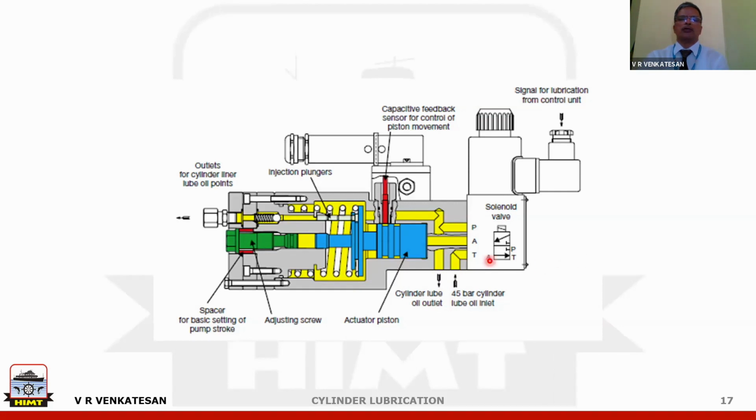So the principle of timed lubrication is that the cylinder lube oil should be delivered as the piston ring pack is passing the quills. So the idea is to deliver the oil into the ring pack. For that, timing is required. MAN always attempted timed lubrication, even in the mechanical design that was there. So timing is better.